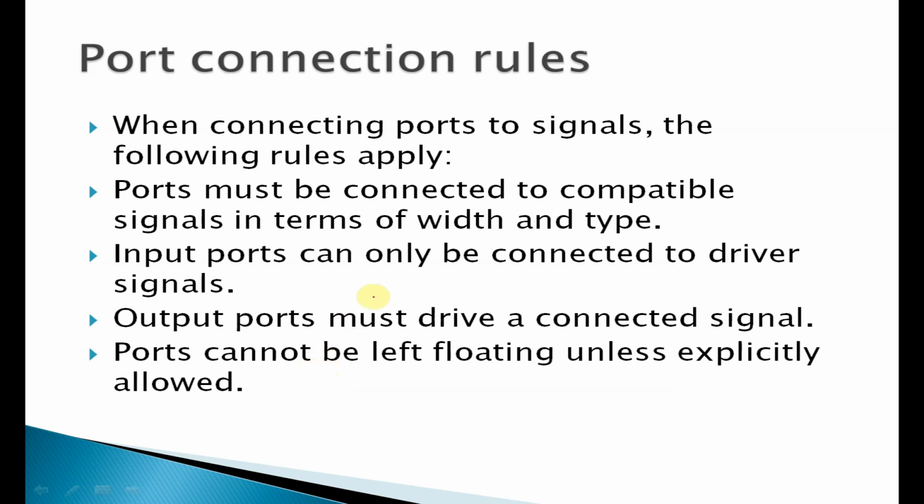When connecting ports to signals, the following rules must be applied. First rule is ports must be connected to compatible signals in terms of width and type. This we will see in detail. And input ports can be connected to driver signals. This also we will see now. And output ports must drive a connected signal. This also we are going to see. And ports can be left floating unless explicitly disallowed. Okay, so all these points we are going to see in detail now.